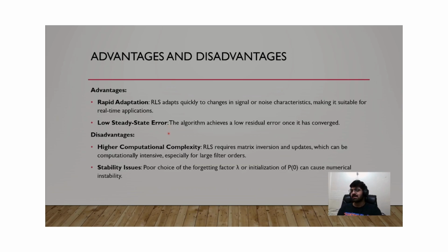One disadvantage is that RLS requires matrix inversion and updates, which are computationally intensive, especially for large filter orders. It requires a very strong computer system in order to operate. Then we have stability issues. Poor choice of the forgetting factor lambda or initialization of P0 can cause numerical instability and not give us the desired result.